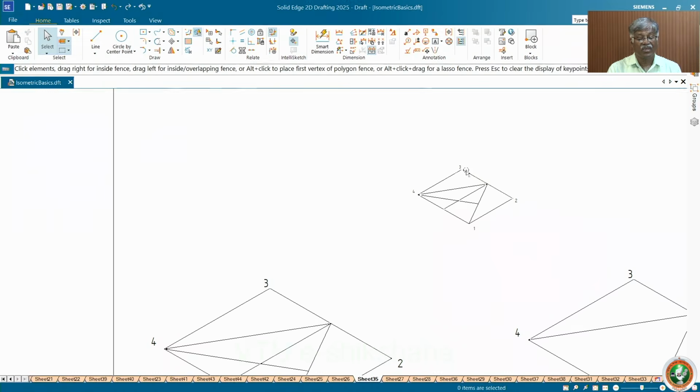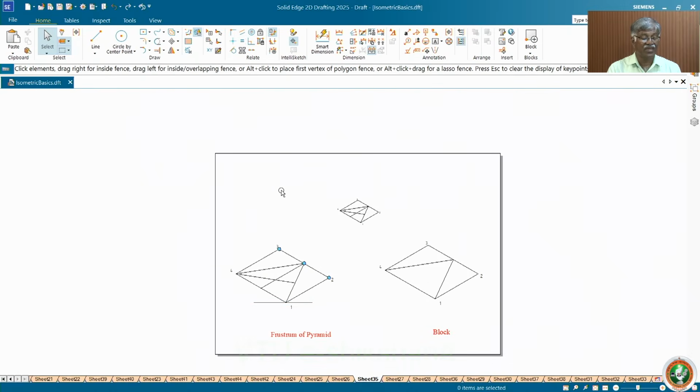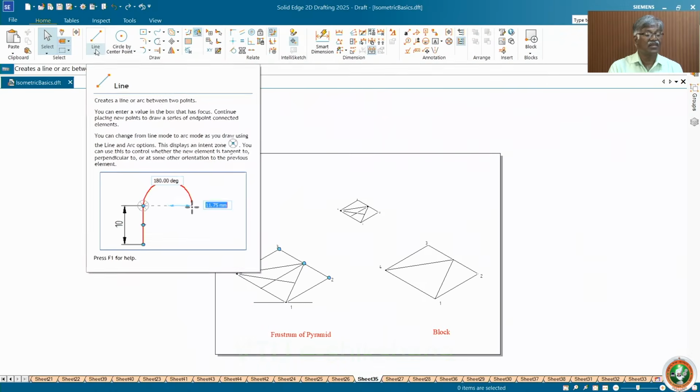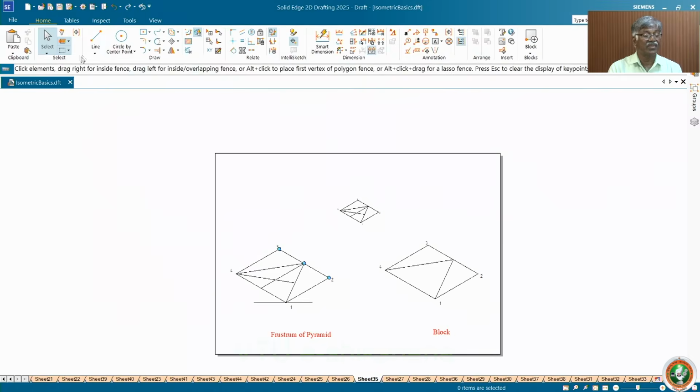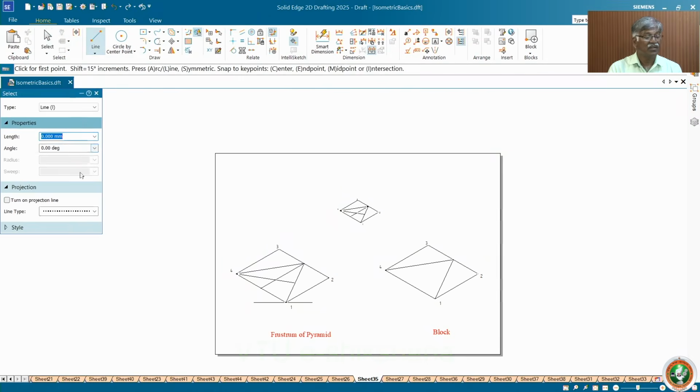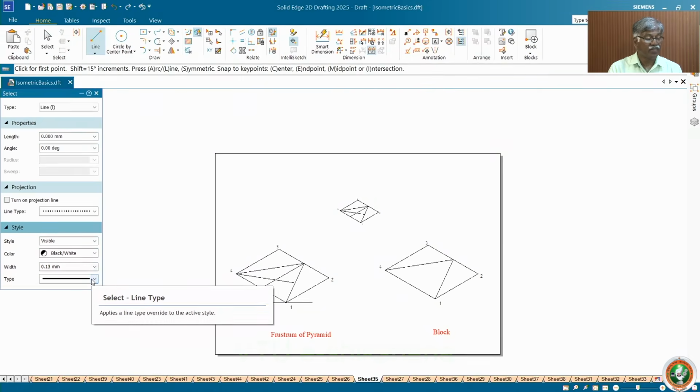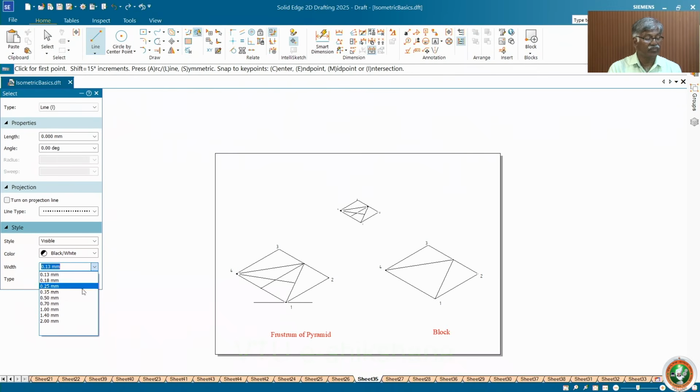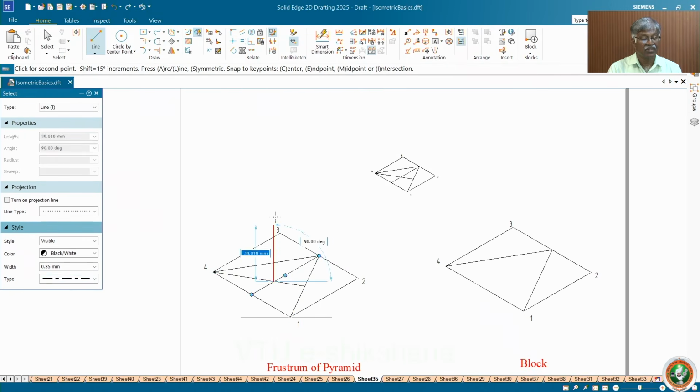Okay, now you have to place it here somewhere. What is that place? Top of the axis. Okay, so axis say 60 mm. I select 60 mm as the axis length. So line axis type, 0.25 or 0.35, and axis, yes, from this intersection, that is center OB, you identify 60 or 80, no problem, 80 mm, enter.